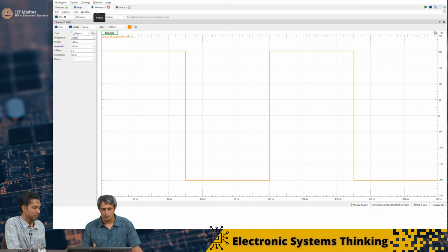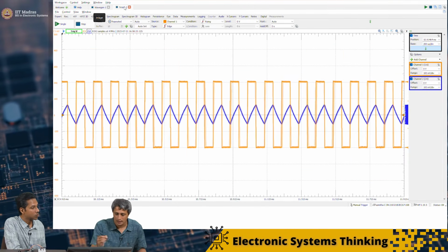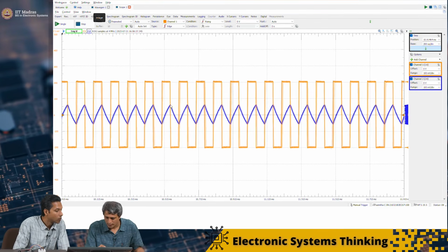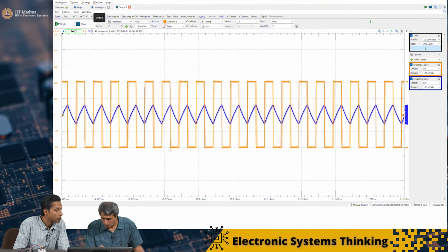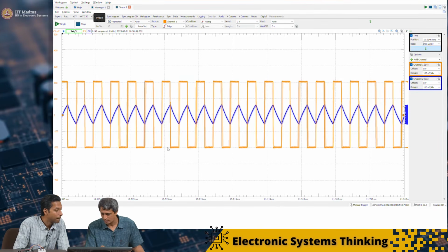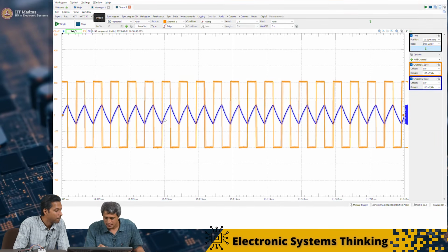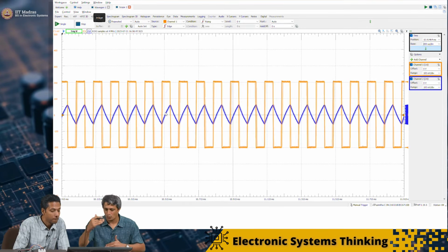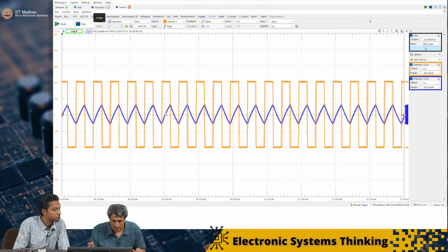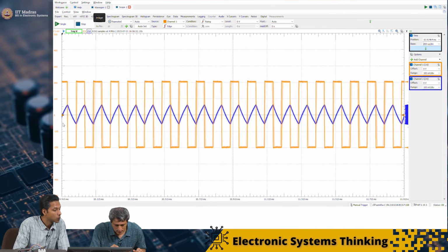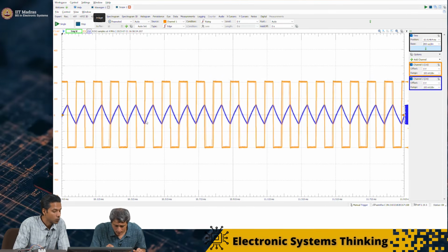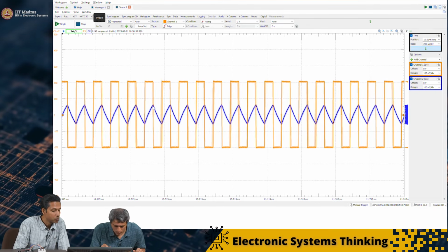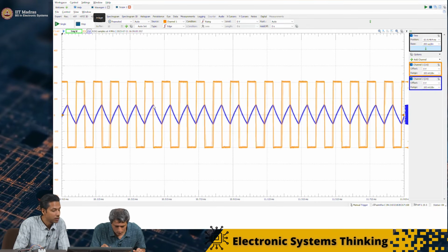So if you look at this, at the maximum value, at 50 microseconds, which is where the half period is, it cannot go beyond 70. The swing cannot be over 70 millivolt. And therefore, this is starting at minus 50 and going up to plus 50.